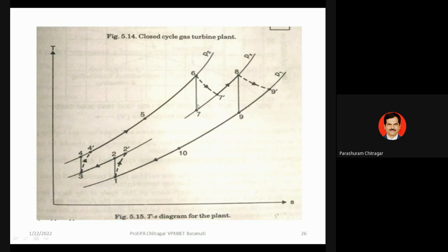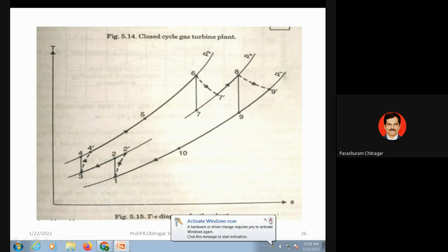मतलब ये पहला वाला टर्बाइन जिसको हम लोग बोलते हैं कि हाई प्रेशर टर्बाइन. Why high? P2 is higher than Px and Px is higher than P1. तो 6 to 7 is isentropic work of a gas in a turbine. Then what is 6 to 7 dash? It is actual work done in a turbine. Now with this, T6 और T7 का एक डेटा है टेम्परेचर डिफरेंस, T6 minus T7 और T6 minus T7 dash एक टेम्परेचर डिफरेंस है. तो ये दोनों यूज करके can you able to calculate the efficiency of a turbine?